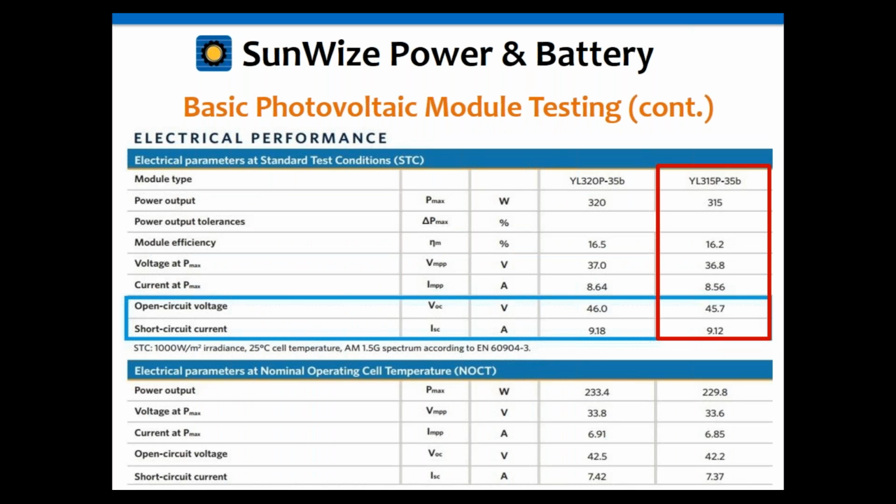One of the things to keep in mind is that if you're within about 10 or 20% of the rating, you're probably close enough to understand what's going on. Solar modules themselves will derate over time, somewhere between 0.5% and 1% per year, so there is a natural degradation on the output of a solar module. However, that is a very slow degradation.